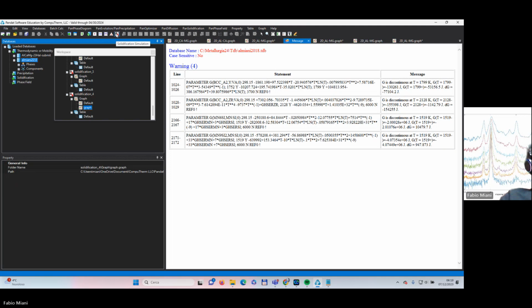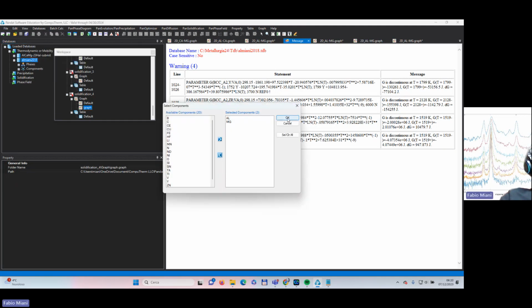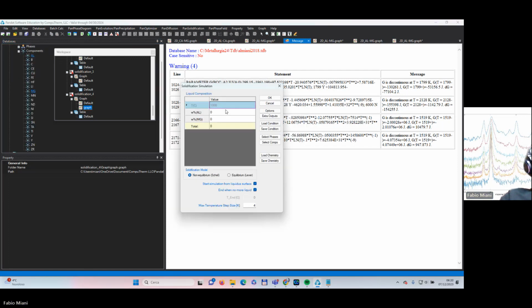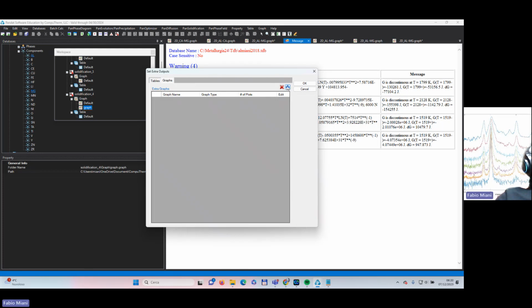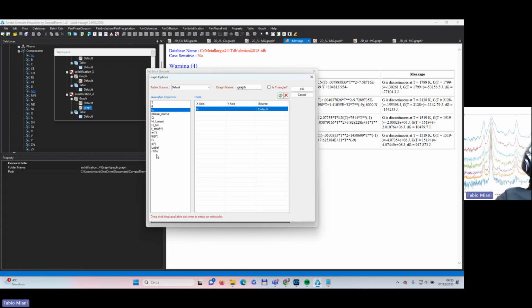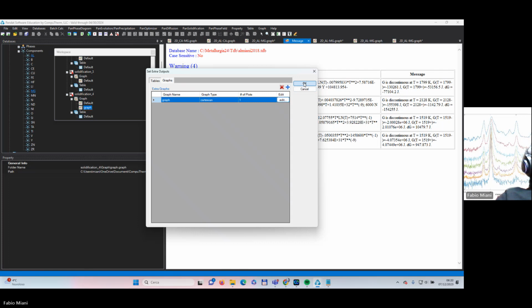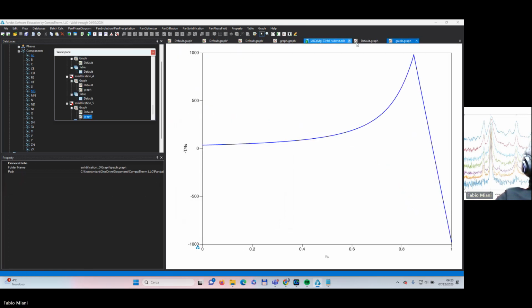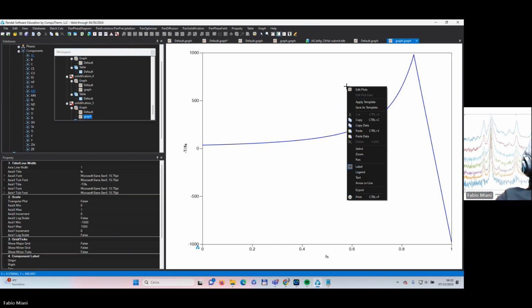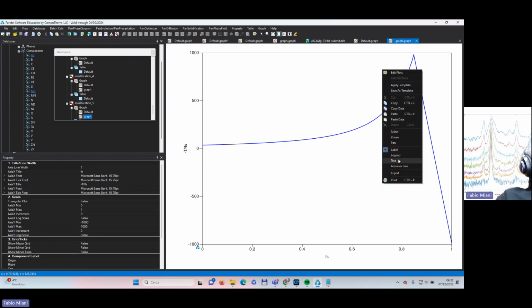And then we will use select components, and again, aluminum, magnesium, and then again this solidification simulation with magnesium 10%. And then we need, again, to check if our extra outputs, so the derivative, has been inserted there in the table editor, and possibly the information on plotting the graph has been lost. So we are re-adding the graph. And for the moment, we check if the two slopes, so let us add a legend somewhere.